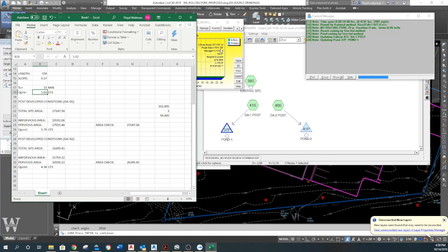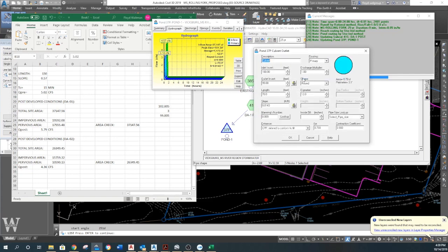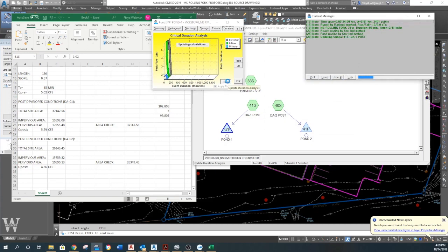What I'd like to do, we're only at 101.3. So what I'd like to do is let's just make this an 8-inch pipe because it's cheaper. Okay. And check our duration again. Notice it came down a bunch. The pond's going to get fuller, which is fine because it'll just flow right out of this pond pretty quick. In fact, I'll show you in just a second, it'll tell you when the pond will be empty based off of free flow and discharge.